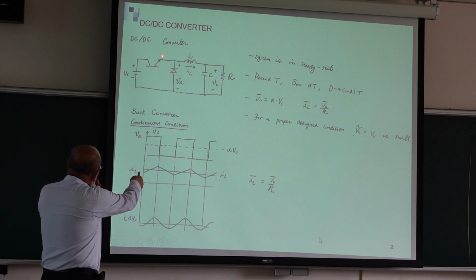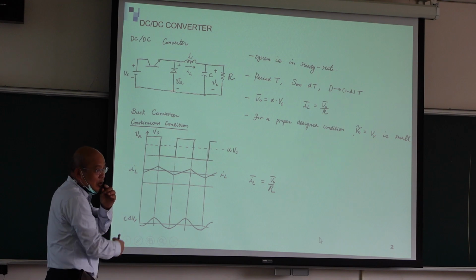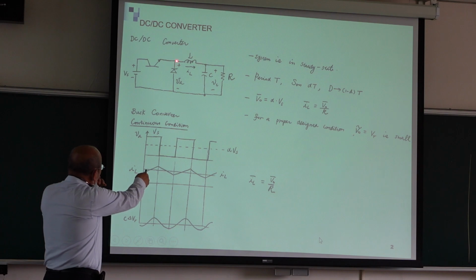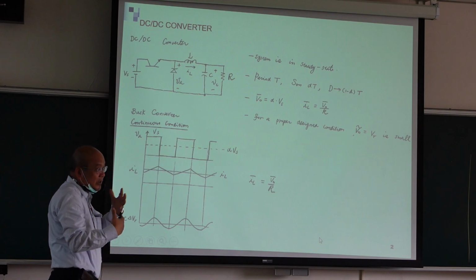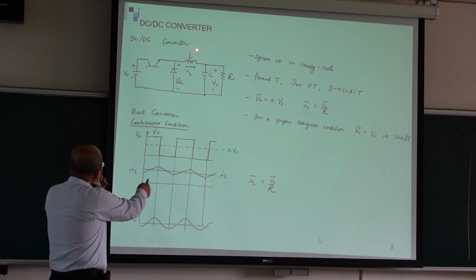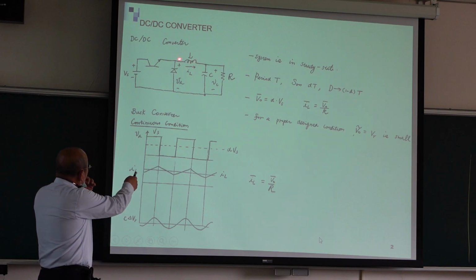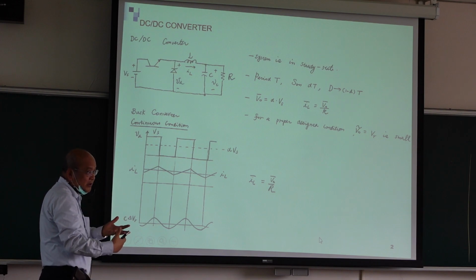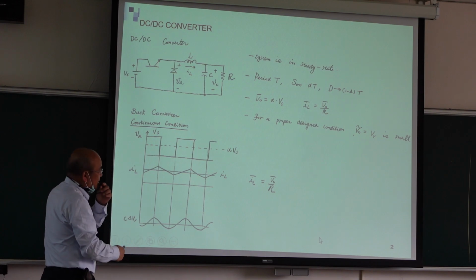If the MOSFET turns off, then the Schottky diode should turn on. Then we can keep the current as a constant current. So we learned this before. Because for inductor current, you cannot make it disconnect. Otherwise, you create a huge spike, right?